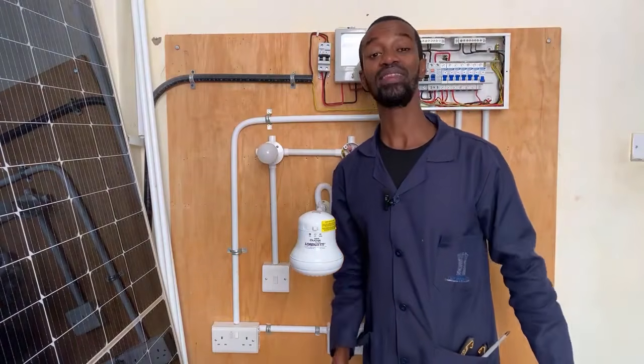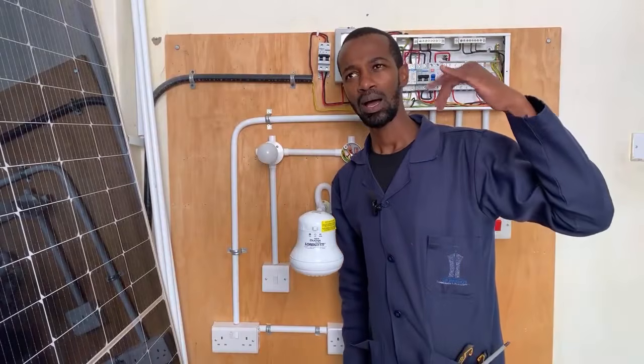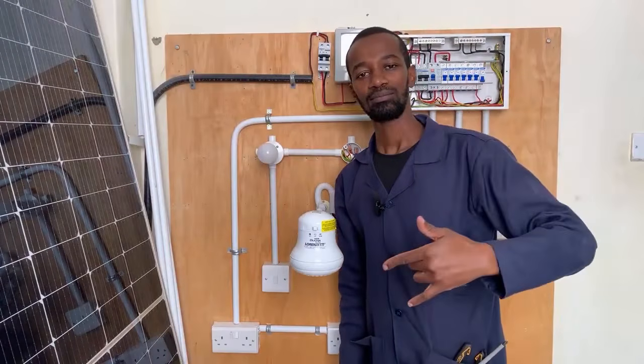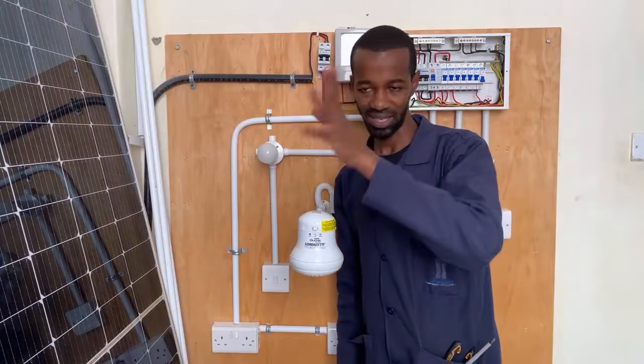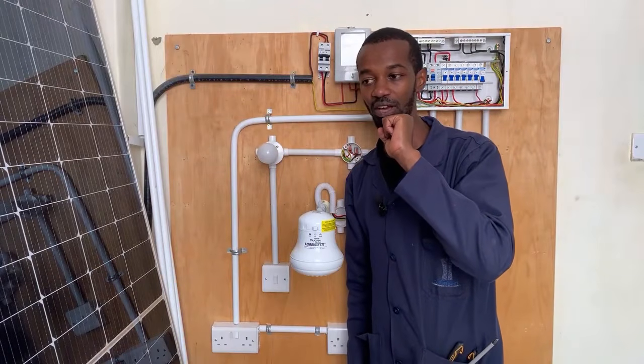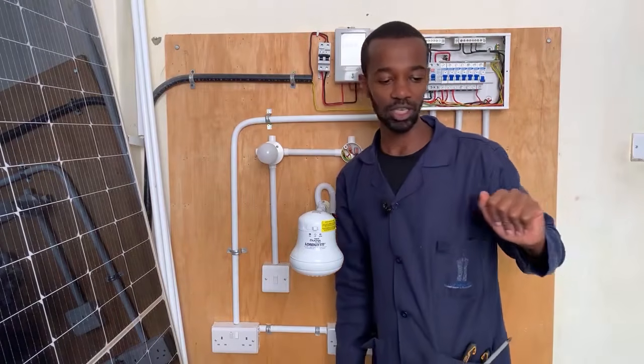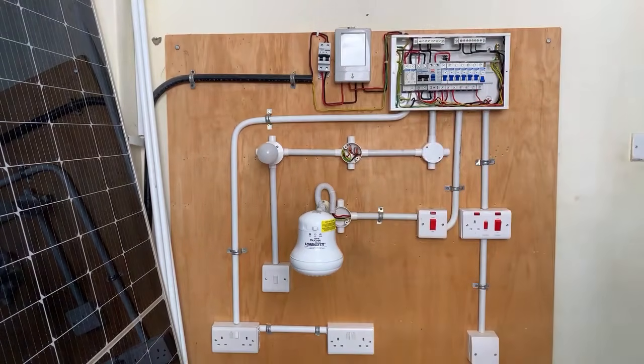Now this is where the juice is. A customer has called you and told you, my lights are not working, be it in the bedroom, the sitting room, a section, they are not working. If you are smart enough, you ask the person, is the TV on, is the fridge, the microwave in the kitchen on, are all the sockets powering on? They say yes. Now what you need to do there, my top boss, is simple. You need to check where the problem could be.